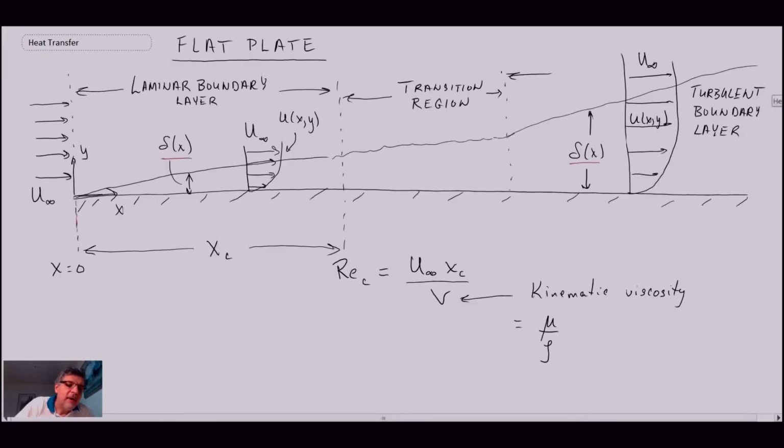One other thing that we should take away: we can perform analysis on the laminar boundary layer. However, we cannot perform analysis on the turbulent boundary layer. For that, we try to do it using numerical methods. Direct numerical simulation is really the only one that truly is able to replicate it. But for the most part, we end up using different experimental values that are tweaking a numerical solution, or we just go and do experiments directly.